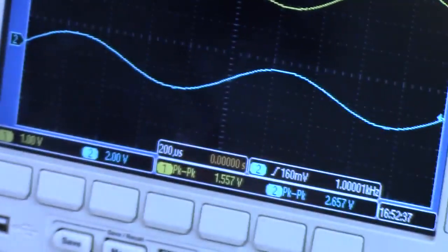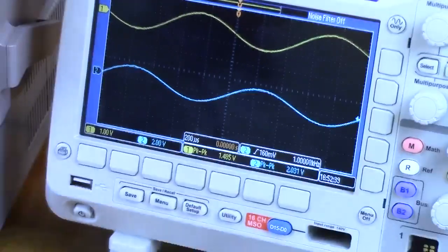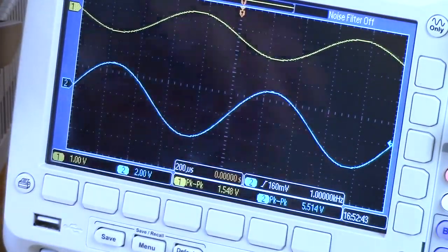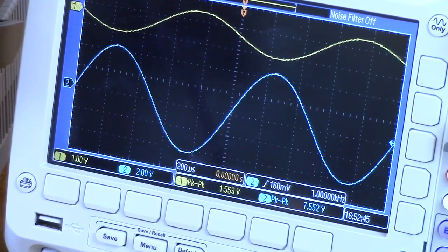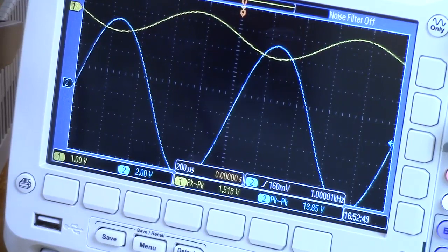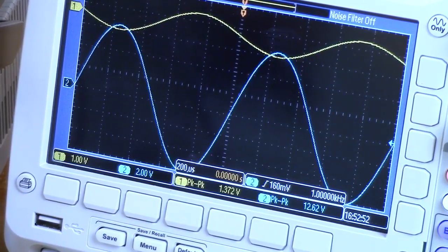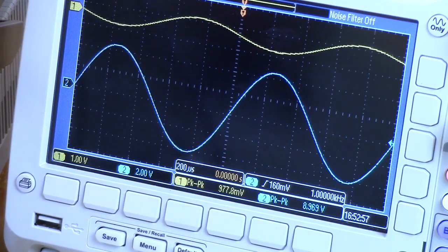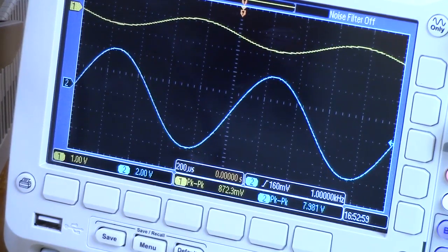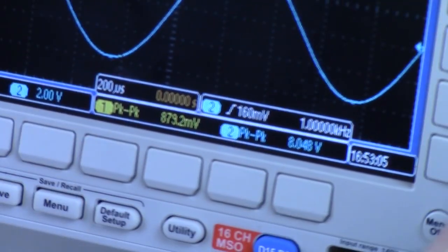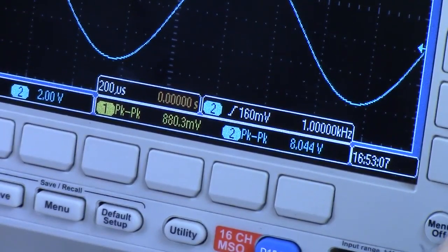Okay, and I did forget to center this pot. Luckily, there's RC in series with it. It's not going to hurt it. So we're going to unplug the pot, set our signal for about 4 volts, 4 divisions peak to peak. About there. 4 divisions peak to peak. Let's slide it down just to here to get good alignment.